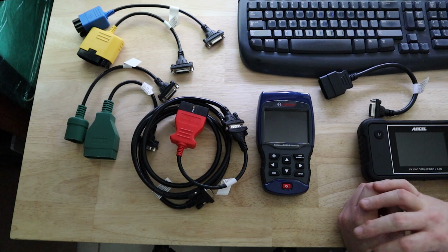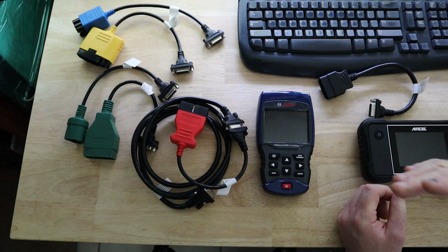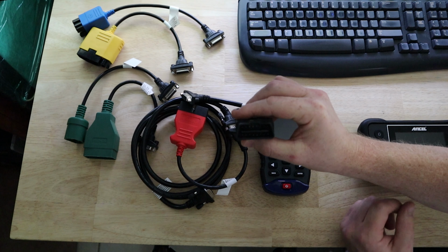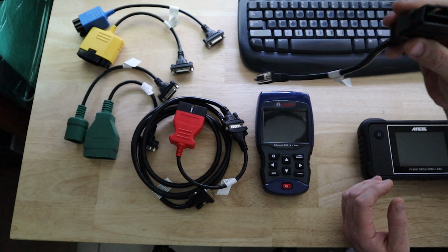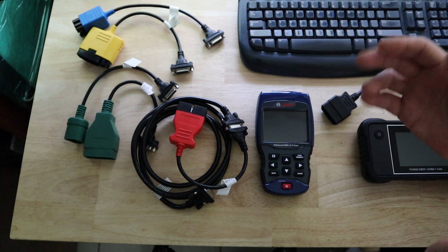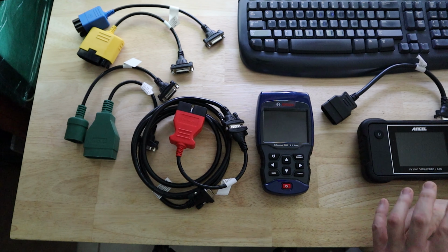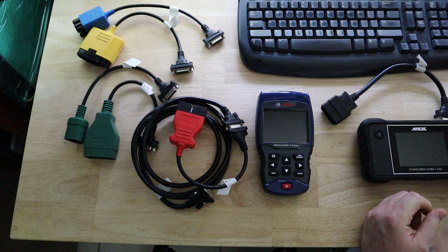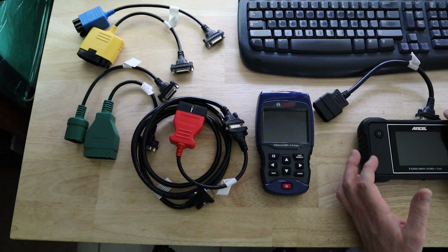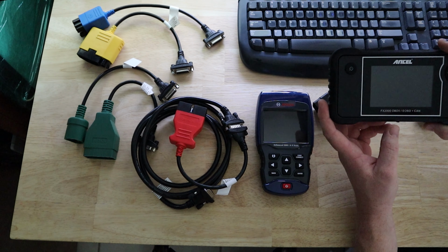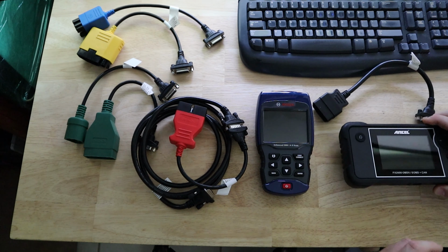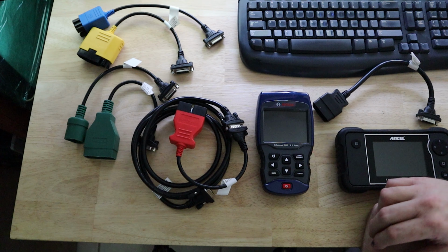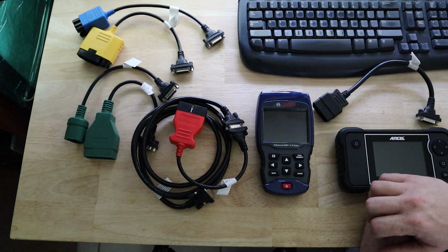But I do have OBDII vehicles, and again, that's from 1996 up, and they use the specific OBDII plug, and this is on every vehicle. They don't change the plug type between OBDII. It's more of a baseline universal code and connector system. You can see this one does OBDII, and it says EOBD and CAN. CAN is just a way that manufacturers use to transfer information via a CAN bus.